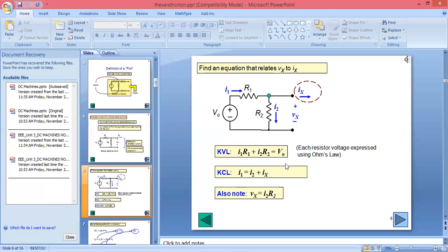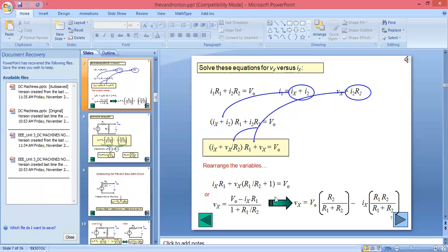So here we will get the value of the voltage across the load. That will be Vx, which is in parallel with this R2. So you can take Vx equal to the voltage across this R2, that is I2 R2, because in parallel the voltage will be the same.